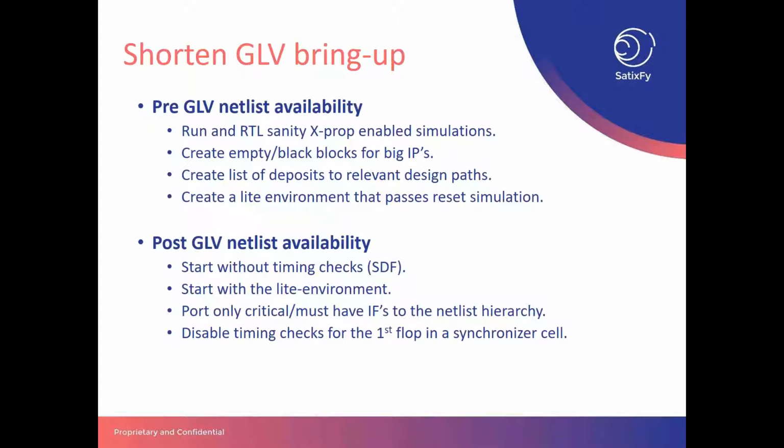Now that you already have a gate level netlist from the physical design team, you would like to start without SDF in the first place. SDF annotates the timing values from the physical view of the design. It's a standard delay format. So you would like to start without it. Obviously, you want to start with a light environment.